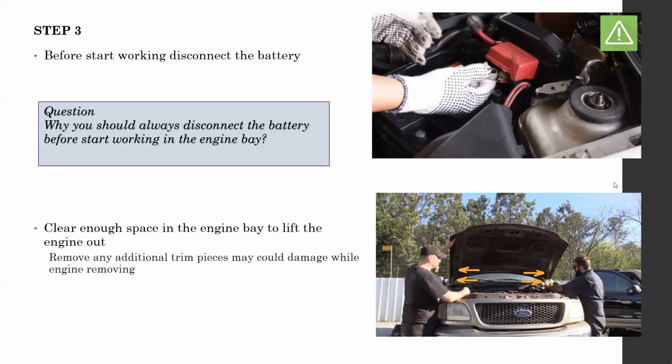The answer is actually, okay, I'm guessing you might remember how the starter motor works, right? In the starter motor, if somehow we connect a positive with a negative, there's a possibility we can crank the engine by mistake with a tool. The tools are metal. There are positive and negative terminals coming into the starter motor.